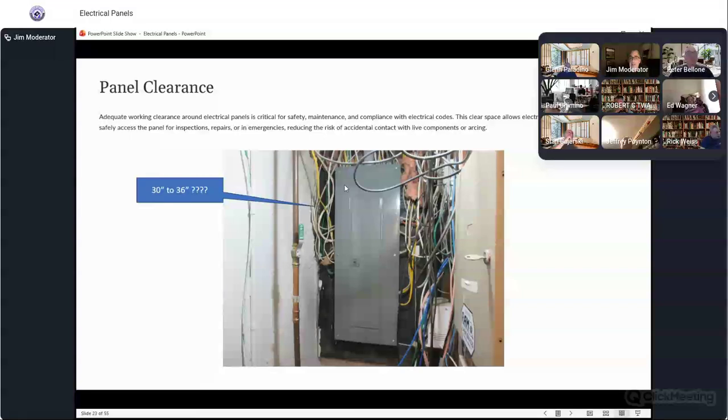Again, here's one I did a couple weeks ago. It was built like that. There's no 30 to 36 inches on the left side of that panel. But look, I couldn't get it far enough away to take a shot, but there's the water line going to the water main. You take 2 steps with that cover off and you're walking into the water main on the floor. Right. And look at that rat's nest there too. That's a mess. Not done neatly.